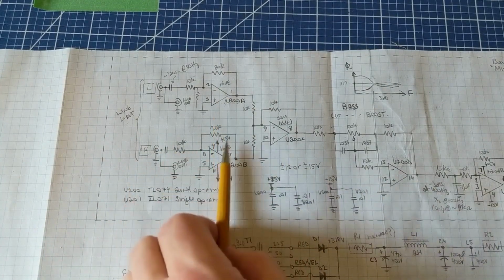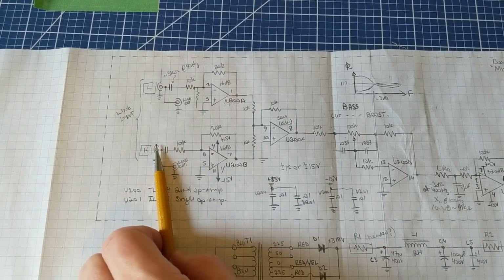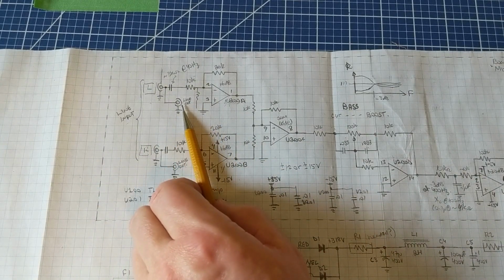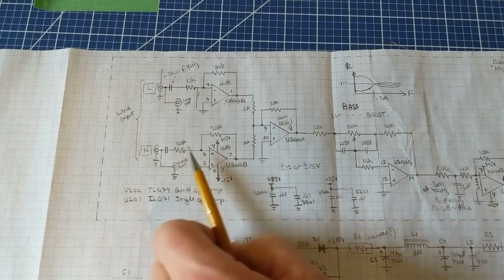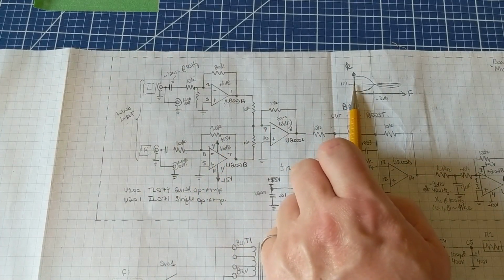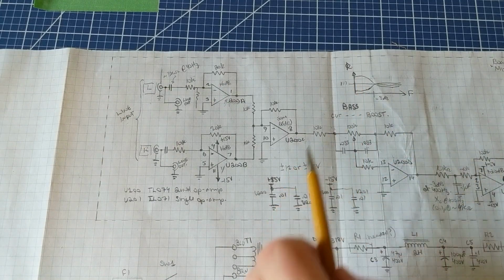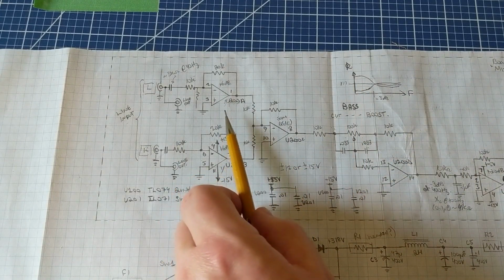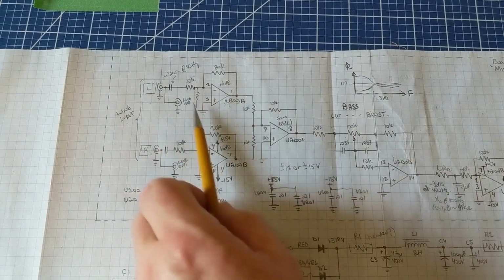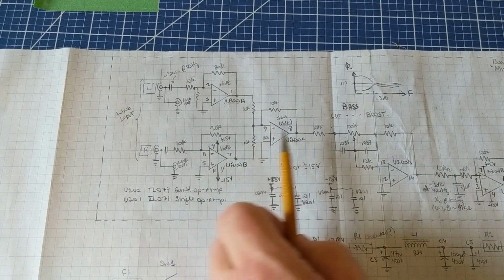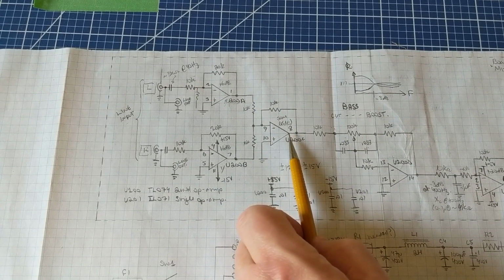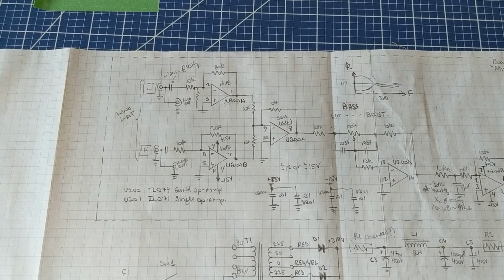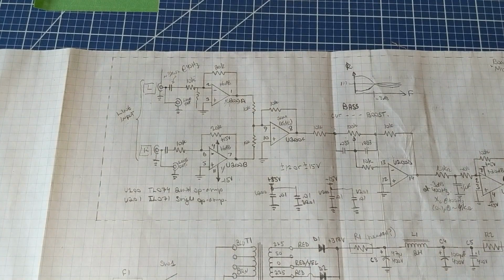I use buffers here to avoid mixing the left and right channels, because you have to remember that these ports here connect to the downstream main amplifier, and I want to keep the left and right channels nicely separated. These are just plus 6 dB amplifiers, or times 2. They feed into a summing circuit, which is actually a negative gain summing circuit. It doesn't really matter. I'm just flipping the phase back and forth, but the phase only really matters when you get to the latter half of the design.